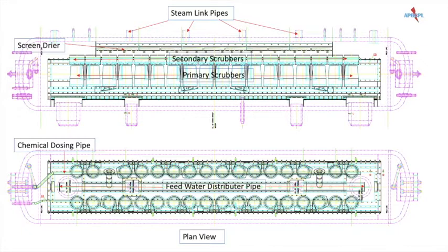The chemical feed lines introduce chemicals in a manner which ensures rapid mixing with the feed water. The chemicals are generally added in a concentrated form, and it is necessary that the lines be periodically inspected and flushed with clean water to prevent plugging due to reaction and deposition.